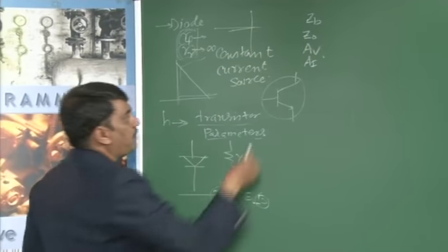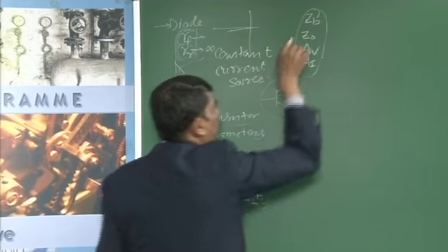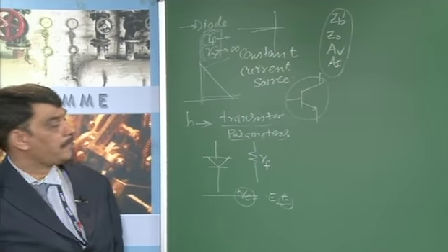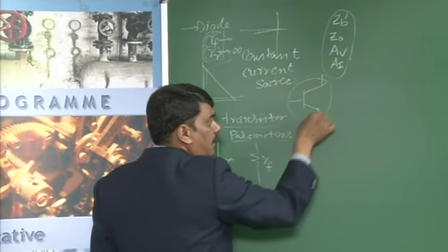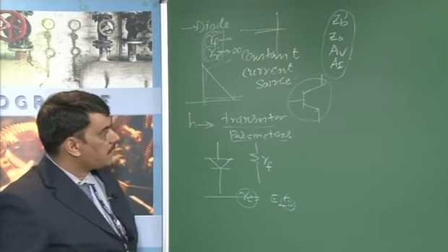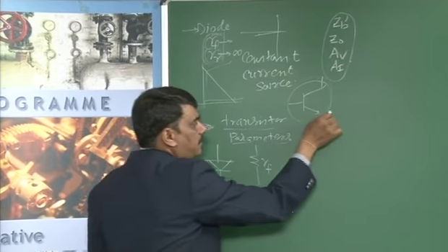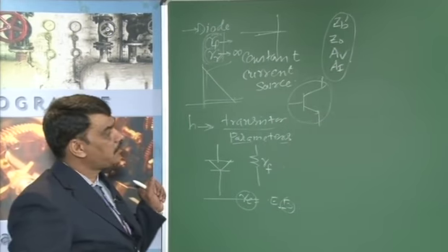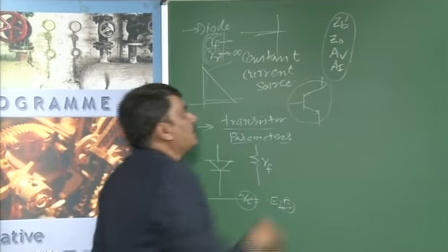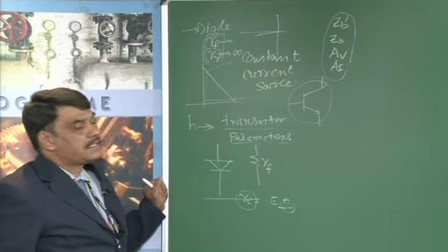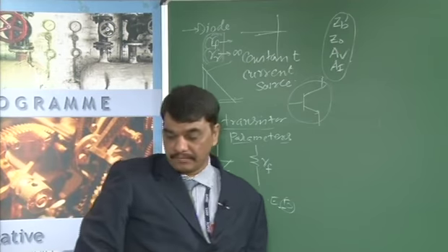These are the 4 parameters you need to calculate. To determine them, first you have to know the wiring circuit or connection diagram, then the transistor is replaced with its equivalent diagram as shown in figure 2c, and then you analyze and calculate the input and output impedances, voltage gain and current gain.